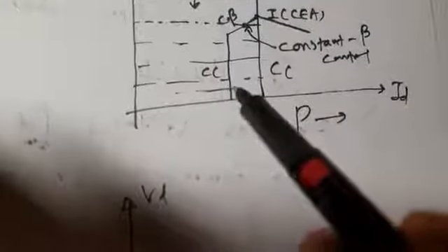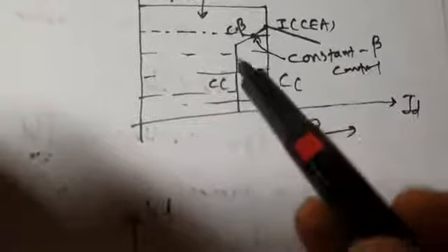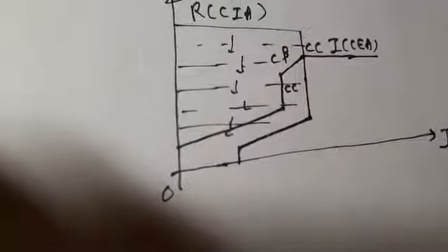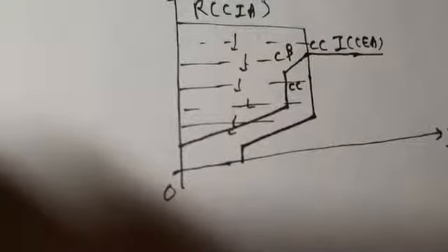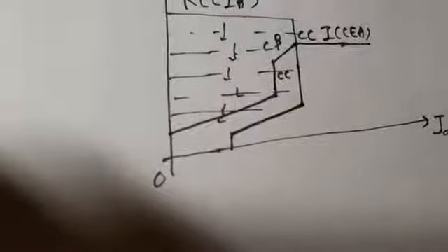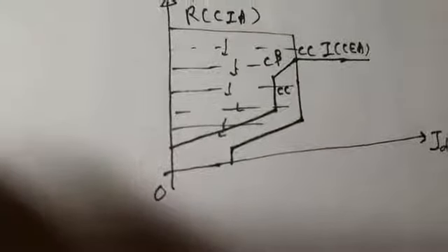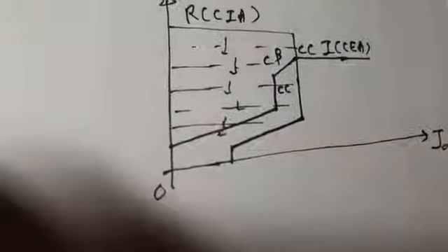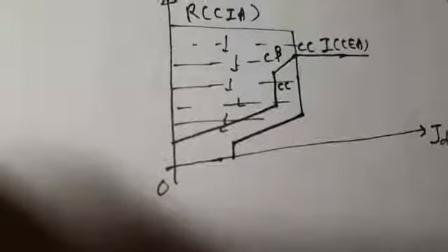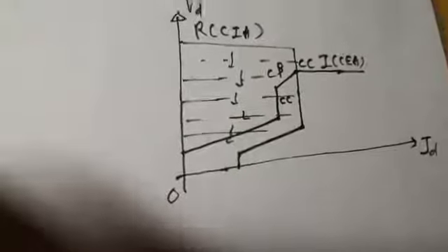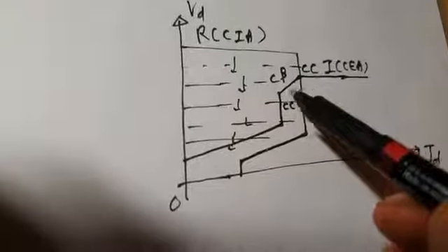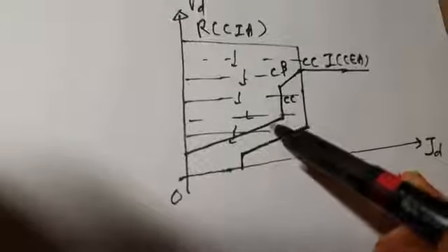So to keep some power flowing in the link under extremely low voltage conditions, your controller will try to increase the current. Because voltage has decreased, it will try to increase the current to maintain some amount of power. But as soon as it tries to do that, the current may go dangerously to excessively large values, and that will cause puncture or damage of the valves of the converter. Converters at both the stations may get damaged. So to avoid that possibility, under extremely low voltage conditions, some limit on the current is kept.